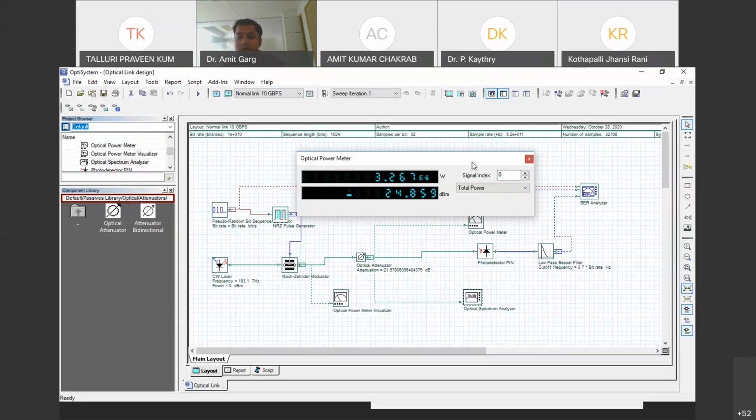Okay, so you must have seen various papers. Those papers compared the results with the back-to-back, and due to some effects occurring inside the fiber. And here I am giving you the idea with the whole effects coming inside the fiber, not individual results. Okay, so due to this 85 kilometers, basically we require additional approximately 4.4 dB of power. So suppose for 80 kilometers, the power penalty is approximately 4 to 4.5 dB.